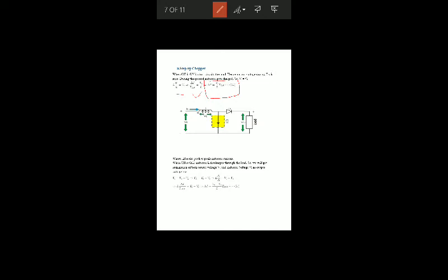In the second case, when the switch is off, the inductor discharges through the load, and we get the summation of both voltage Vs and inductor voltage VL as output voltage. When the switch is open, the inductor will discharge through this load. At that time, the load voltage V naught will be the sum of VL plus Vs. Again we have to compute the value of delta I from this expression.